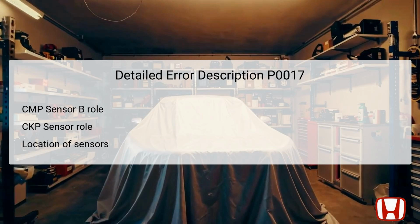The Crankshaft Position (CKP) sensor monitors the position of the crankshaft, providing necessary data on the rotational speed and position of the crankshaft for efficient engine performance. The CKP sensor is typically located near the crankshaft, usually in the engine block or timing cover area. If there is any discrepancy between the signals from both sensors, such as those caused by a malfunctioning solenoid or a timing issue, the system initiates a fault code, flagging a problem within the Variable Timing Control (VTC) system.